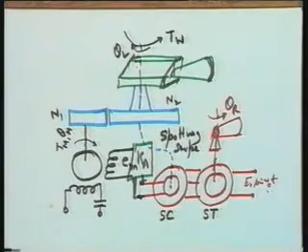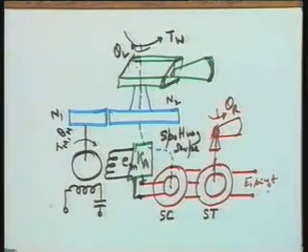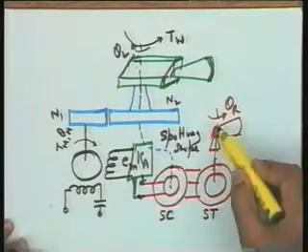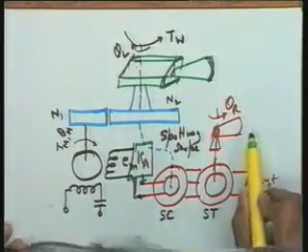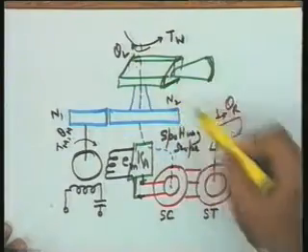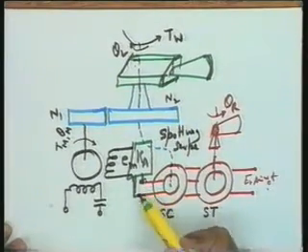So see the nature of the signals in this particular case. Nowhere is demodulation or modulation required, because the signals are of the nature that the devices are compatible. In this particular case, theta_r minus theta_L is a DC signal, and the output of this synchro device is a modulated signal.